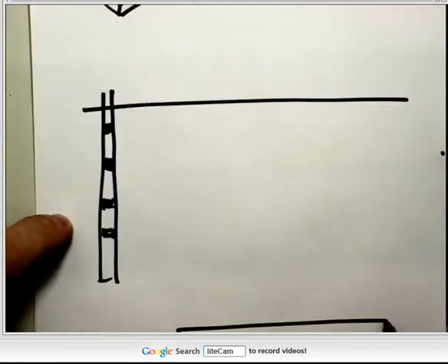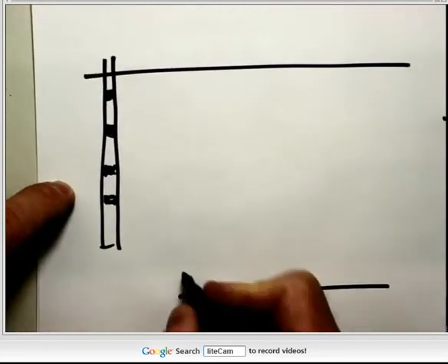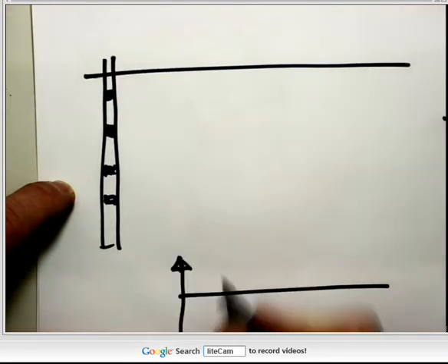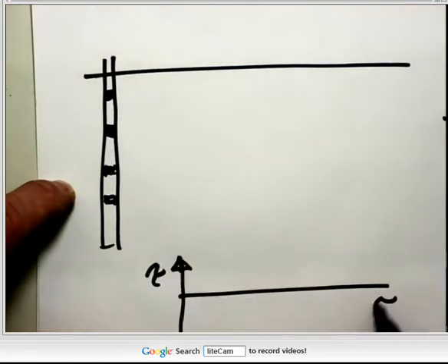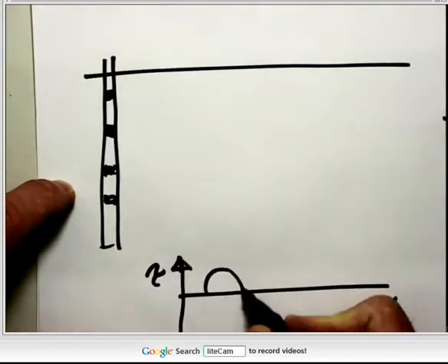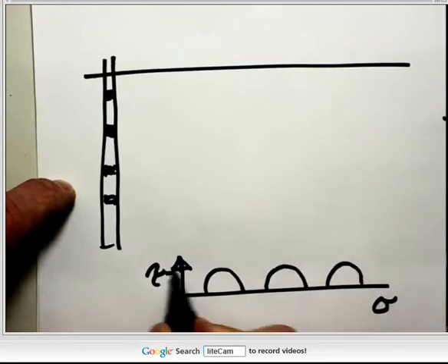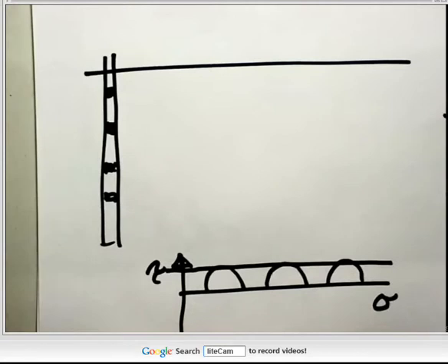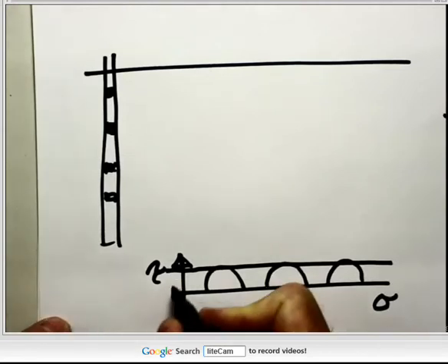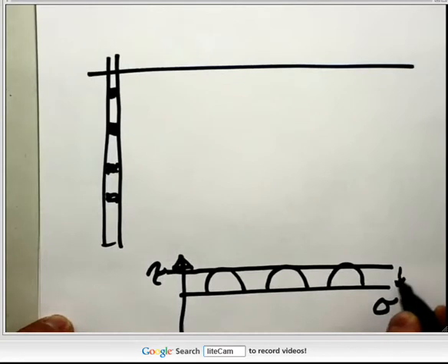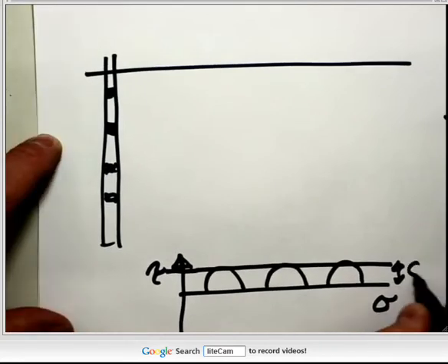So when we plot out tau against sigma, we're going to get a whole series of, I've just drawn half circles there, and we're going to estimate a single value of, I'll label it at this end because I've made my diagram a bit cluttered, Cu.